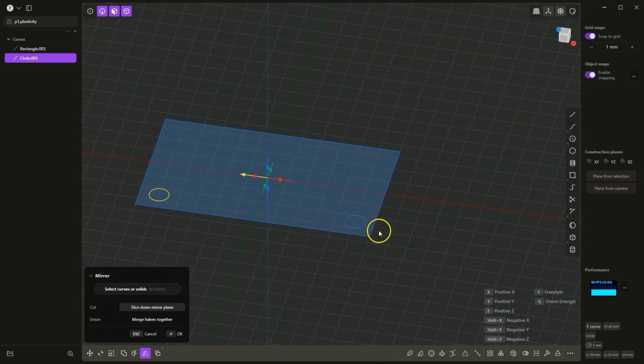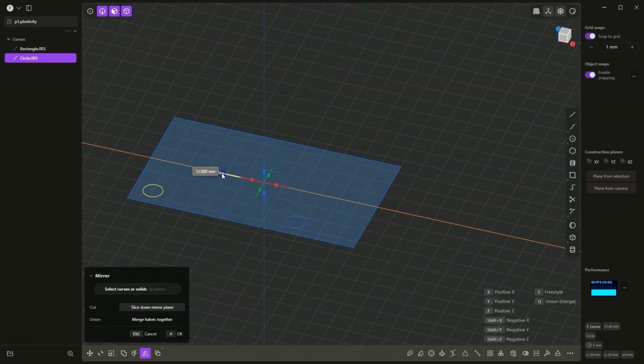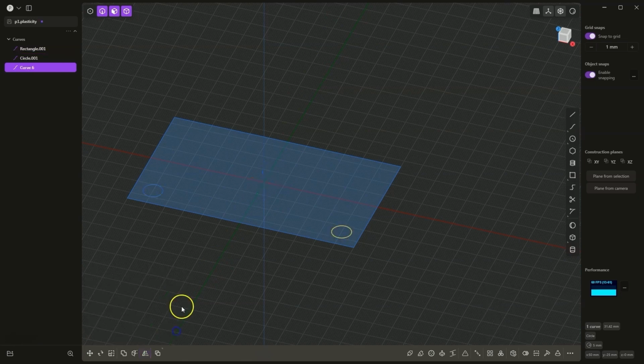This defined the mirror plane passing through the y-axis, because if I drag this arrow, I am moving the position of this mirror plane, and the position of the circle also changes. Here, I returned to the value of 0 so that this plane passes through the y-axis. Regarding the mirror command, we will return to this when mirroring 3D solids, and then these mirror planes will be more visible. Here I click OK, and now I would like to get these two circles in these corners.